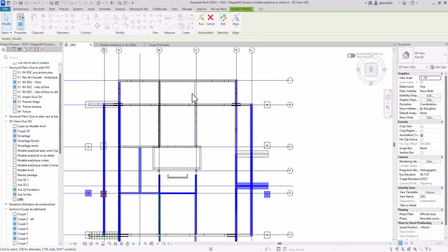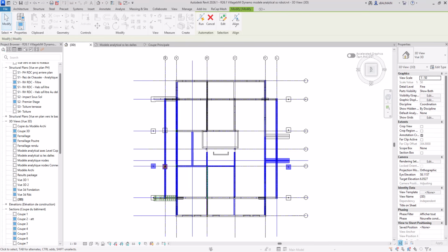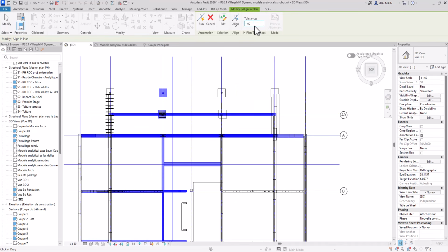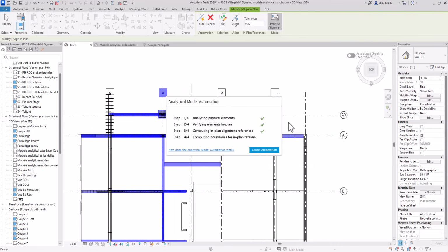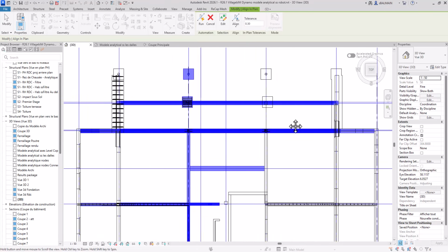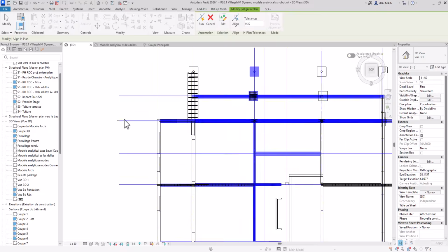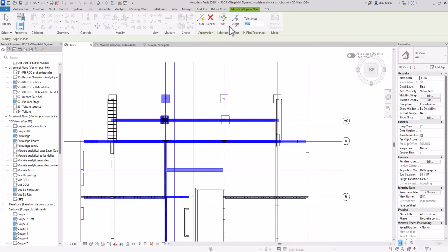In the PowerPoint, I removed the slab, and when I created my view, there were some small openings. So, for example, here if I move to 0.3, I need to create my preview again, of course. Here you see I have 2 lines in blue, and maybe here too. So it's up to you, but I would go for 1.